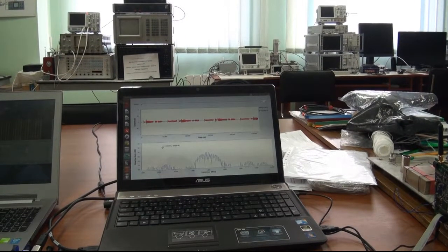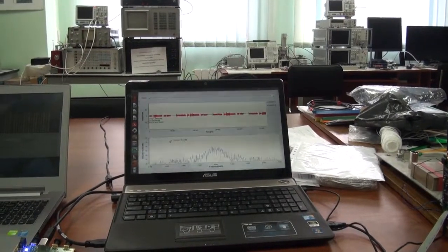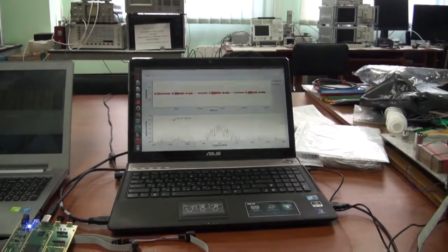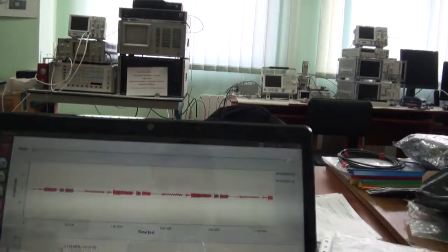Here, signals from both of the links overlap each other and frequencies are the same as in the previous test. Sure, the power difference can be increased, but then qualitative reception from a weaker transmitter cannot be guaranteed, because 15 dB gain is the worst case and a real processing gain for all possible sequence sets of spreading factor 1024 that is used in this case. For sure, processing gain can reach 30 dB respective to this spreading factor in some cases, but generally for wideband interference processing gain is equal to the square root of the spreading factor.